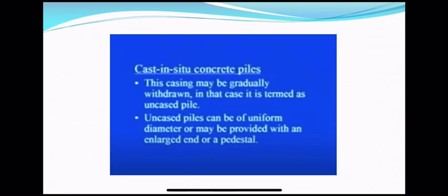So today, I introduced what exactly deep foundations are, and how they are different from shallow foundations as far as the load transferring mechanism is concerned. How they can be classified: end bearing piles, friction piles, compaction piles, etc. Then we saw how, based on the mode of construction, when a pile is being installed and causes a lot of displacement of the surrounding soil, it is called a displacement pile; otherwise it is a non-displacement pile. And then, based on the material of construction, we saw timber piles and some of their main salient features. In concrete piles we saw both